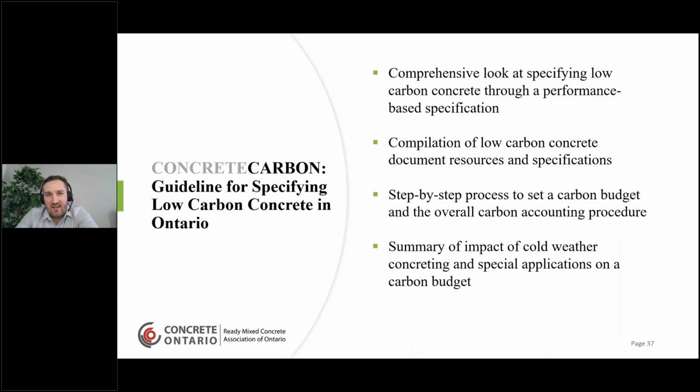And basically, it has a comprehensive look at specifying low carbon concrete through performance-based specifications. It has a compilation of low carbon concrete documents and resources that are available in North America. It looks at things that the Treasury Board of Canada is doing. It looks at specifications that the Biden Clean Act in the US is using. There's a step-by-step process to set a carbon budget and overall carbon accounting procedures. And it does address the impact of cold weather and special applications on a carbon budget.